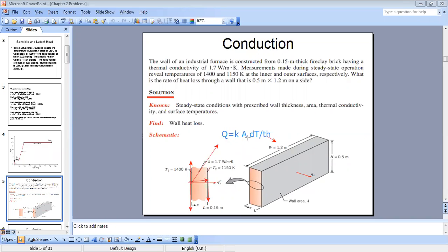So to find the conduction flux, it can be treated as a 1D case. So it's minus K times A times dT by dx. But we have seen that because it's 1D, it's only along one direction, restricted to this term along x, and you have constant conduction coefficient K. You have steady state conditions here.